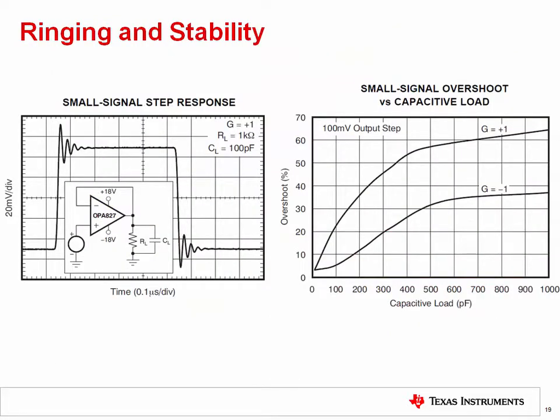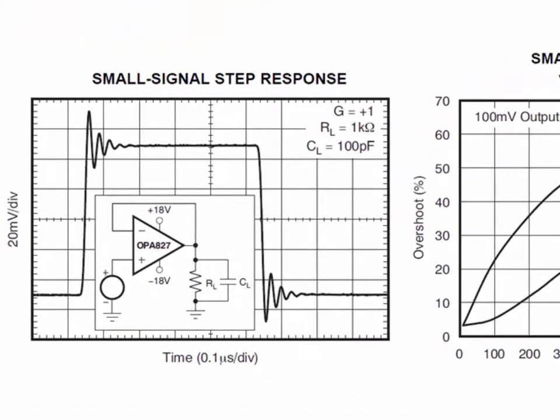The small signal step response can also be used to judge the stability of the system. In general, any second or third order system response, such as an op-amp, can be tested for stability by applying a square wave at the input and observing the behavior of the output. In the case of the op-amp, care must be taken to ensure that the op-amp is linearly amplifying the signal. This means that a large signal input step cannot be used, since in that case the op-amp will be in slew limit and not be operating linearly. Rather, a small signal input step must be used.